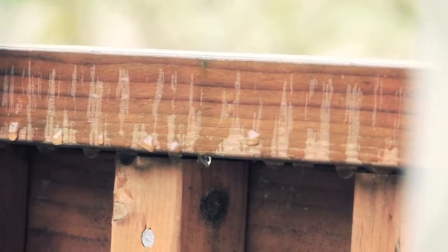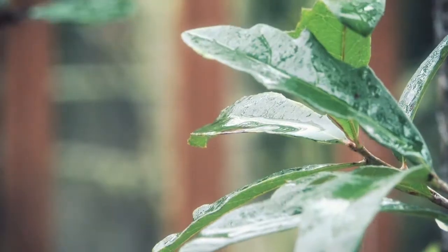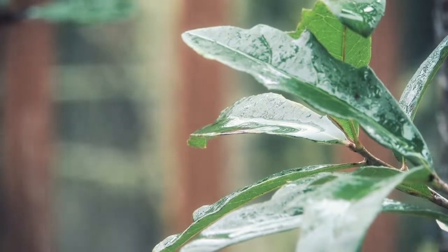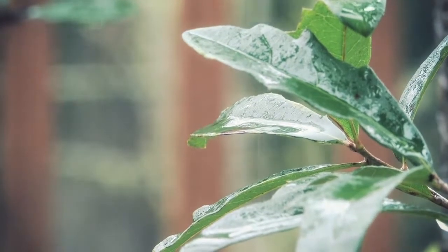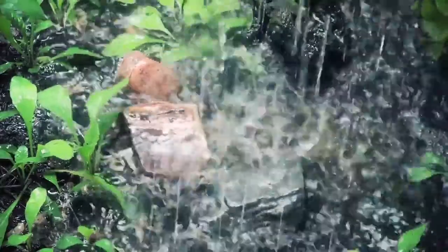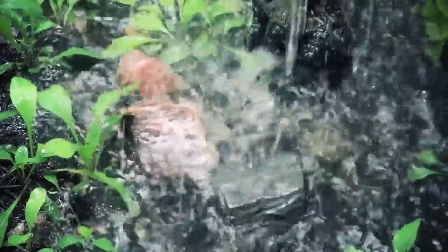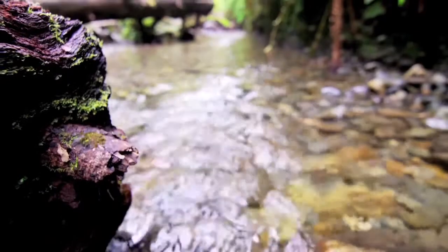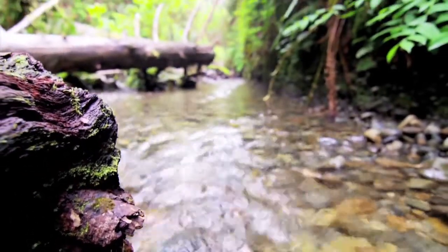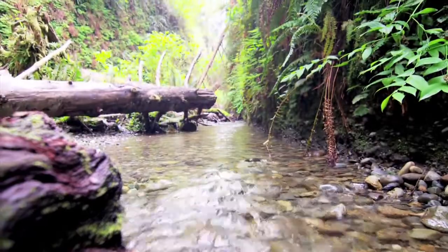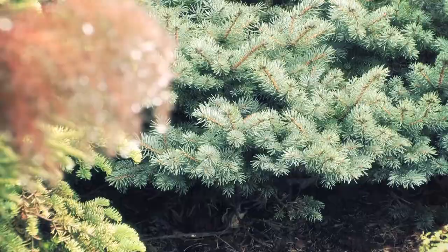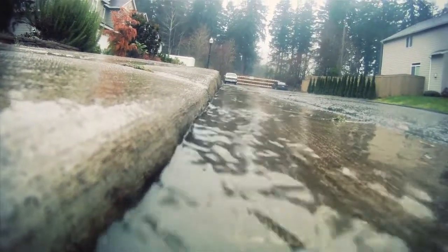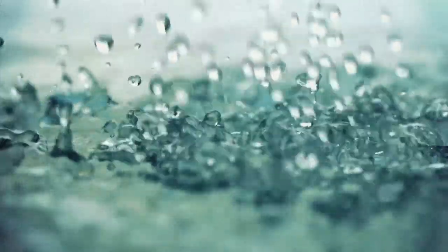Again, the intent of the rainwater management credit is to replicate the pre-development hydrology to protect and preserve both the water resources on site and those downstream. For example, if prior to development 25% of the annual rainfall runs directly into a stream and the remainder infiltrates into the ground, then the post-development goal should be to limit runoff to 25% of the annual precipitation while maintaining the correct aquifer recharge rate.